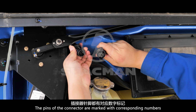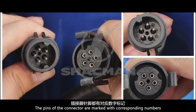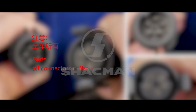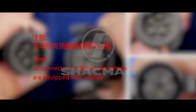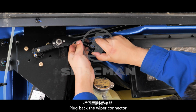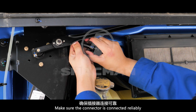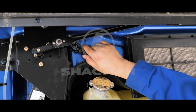The pins of the connector are marked with corresponding numbers. Note: all connectors in the whole vehicle are equipped with latches. Plug back the wiper connector. Make sure the connector is connected reliably.